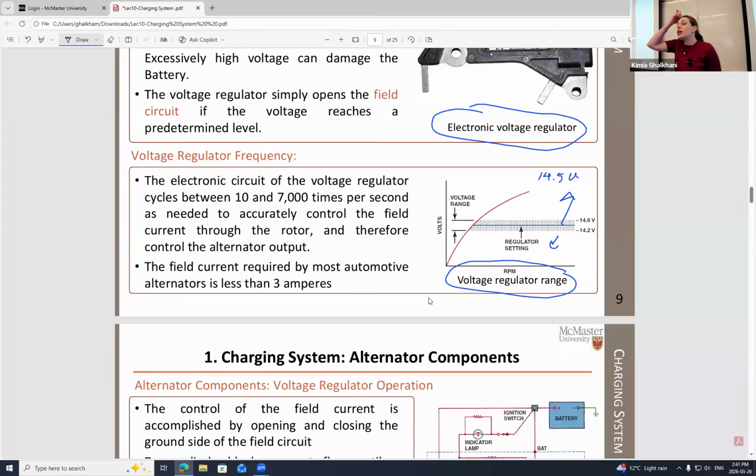a weak battery. So we have a discharged battery, and we have to fix any problem. If it is a problem we cannot troubleshoot, we have to replace the battery. Therefore, you have to have this understanding. The acceptable range, this blue one, should be at around 14.5. Anything above or below, and usually below is at around, I would say, 13.8 volts. So if you have something at around or below 13.8, then your battery is weak and it's time to replace the battery of your vehicle.